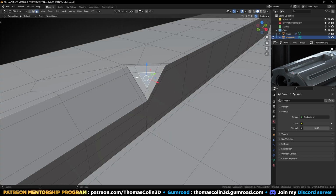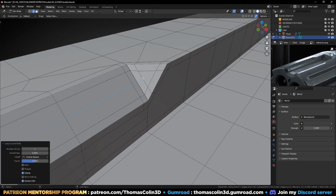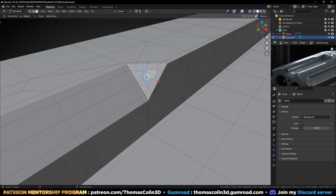To turn this triangle into quads, let's just add a loop there. Select the knife tool by pressing K. Click at the center of the triangle. Hold Shift and click there. Do it again, Shift. And as you can see, if I press Shift, it snaps the vertices at the center of the edges. So click. Now we have 3 quads.